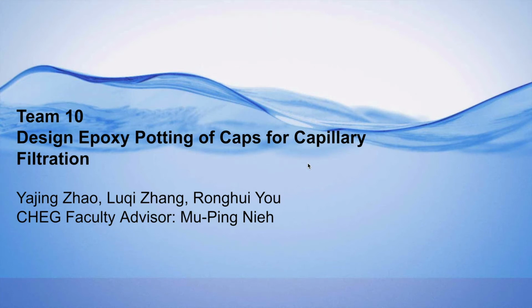Our senior design project is about designing epoxy potting caps for capillary filtration. This project is specifically about capillary filtration because the capillaries are small enough to filter water. A major part of this model is the cap epoxy that stabilizes the bundle of capillaries. The goal for this project is to simulate the temperature profile in the reactor cap as a function of curing time and analyze the temperature profile under different parameters.